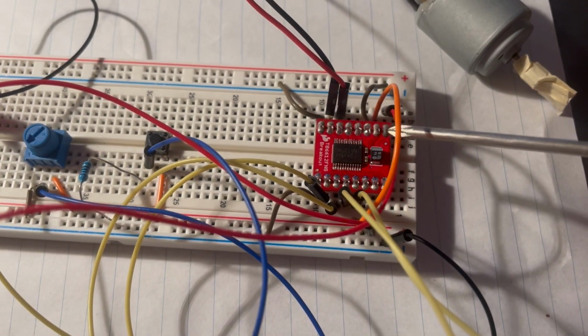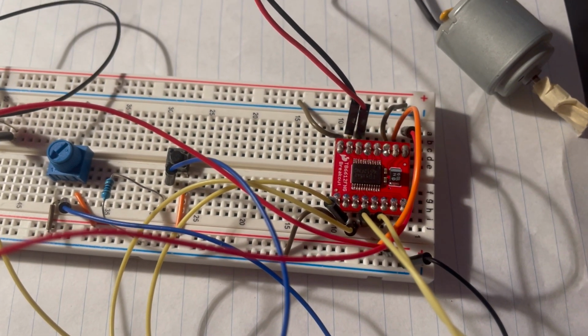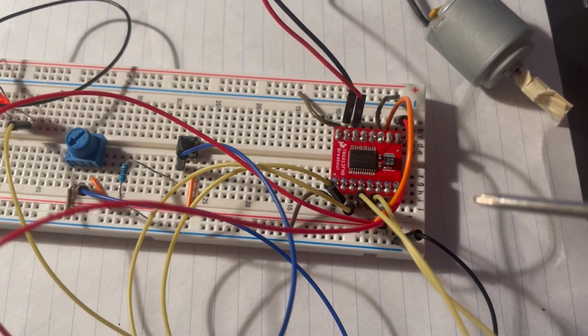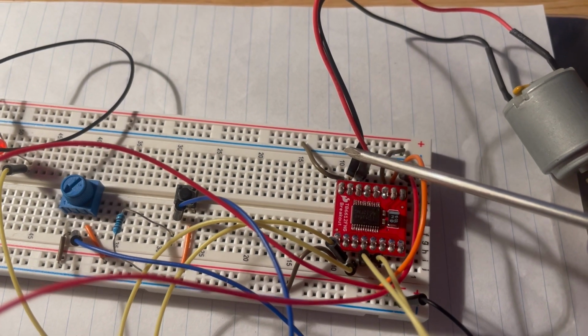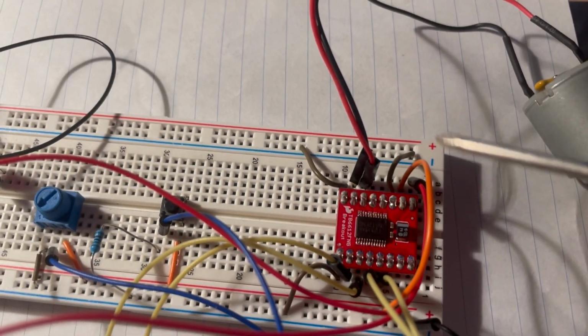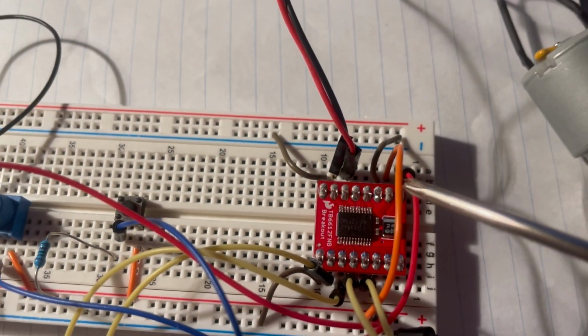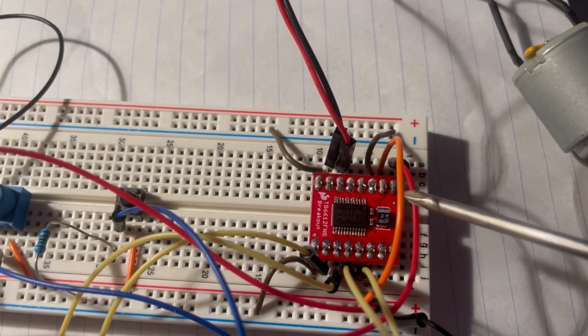So here's the drive, and you can see that it looks fairly different from the integrated circuit that I was using for the Tinkercad demonstration. And you can see I have the motor with its power and ground. You have the 3.3 volts of power used to power the board, and you have the 5 volts of power coming from the board. And I forgot to mention, this does need to be 5 volts.